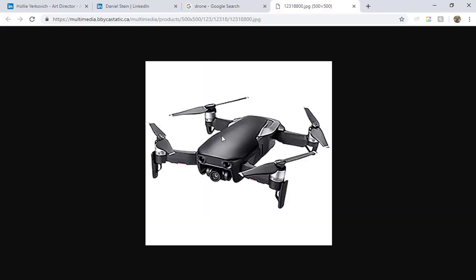All right, so the first thing we want to pay attention to is that this is basically a symmetrical item, right? Like if we were to half this and then half that again, we basically have this corner piece that is the same thing on all 4 sides. Ignoring some things like maybe this cavity where the camera is, might not be on the other side. The least amount of work we can do, the better. So if I can model 1/4 of this and have Cinema automatically copy it to the other 3 sides, that's the best thing we can do, okay? So we want to set that up as well.